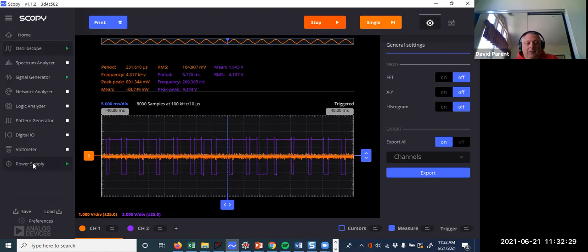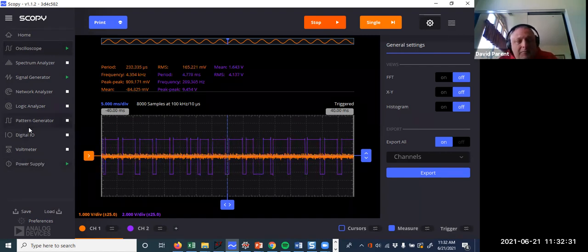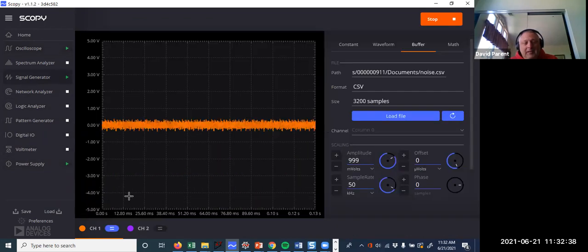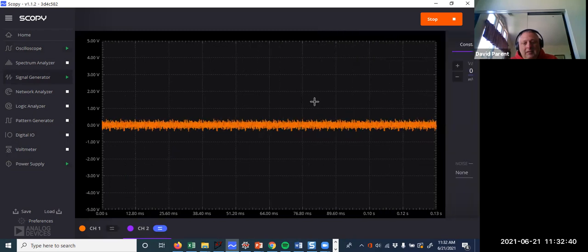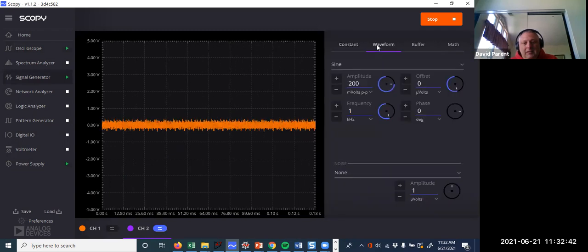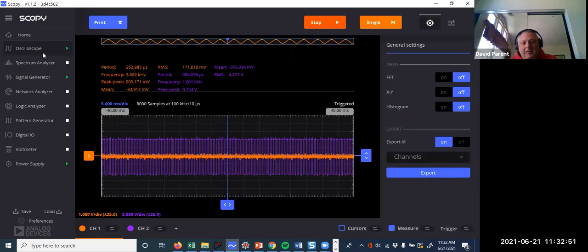Now the other side is what can happen is your peak to peak input might just be causing it to trip. The sine wave is so large that it's making it trip according to the sine wave, and the noise isn't assisting it.